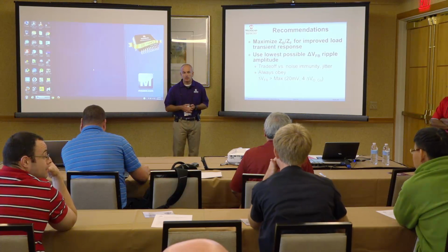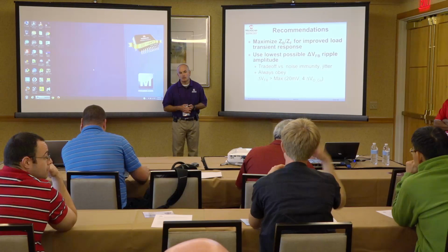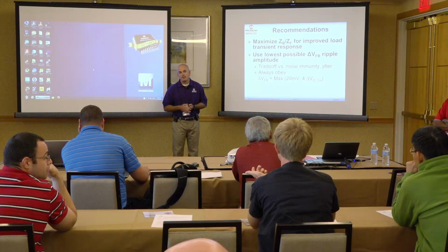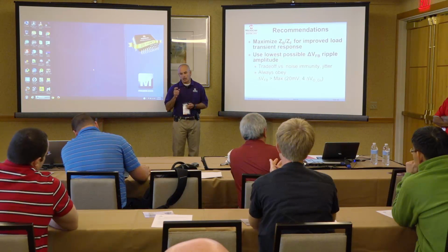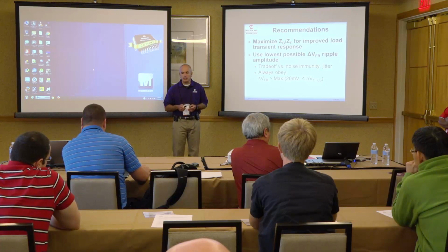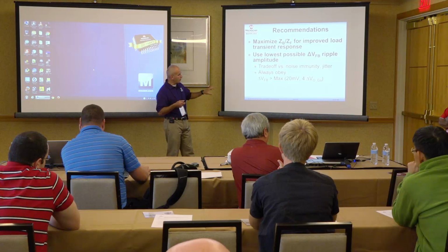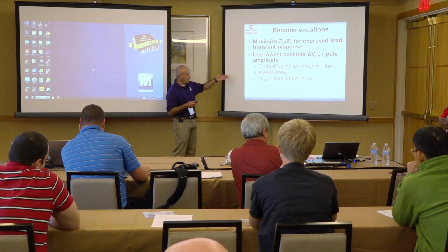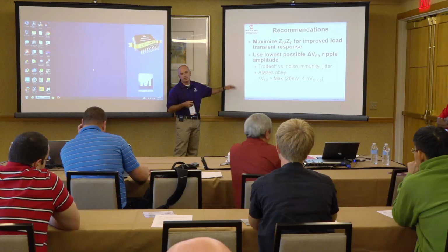So it's a trade-off between stability and performance. You try to maximize, but if it's too big, then you get stability issues. If you go lower and lower in ripple self-injection, you approach the instability boundary.